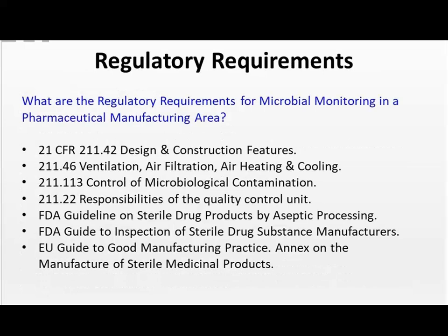There are also other regulatory requirements for microbial monitoring. Your 21 CFR 211 deals with design and construction features, which are very important. Your equipment has to be a certain design. It has to be certain materials of construction to go into your clean rooms. 211.46 covers your ventilation, your air filtration, your air handling units. 211.113 covers your microbial contamination, and then 211.22 gives you a list of responsibilities for the quality control unit.